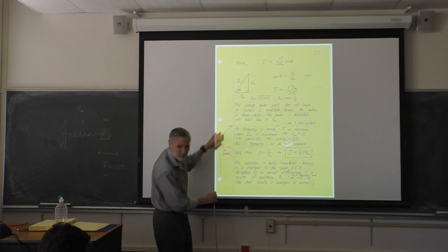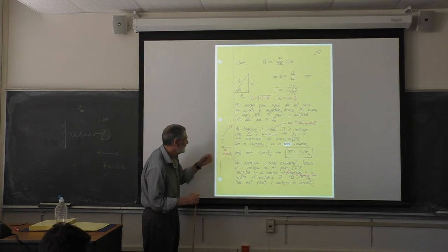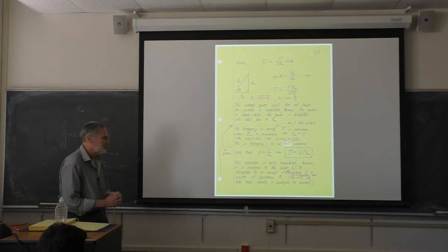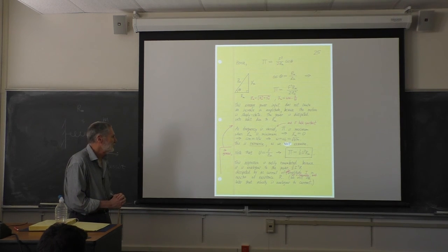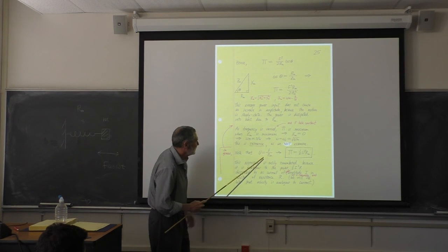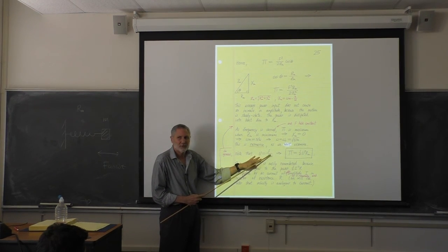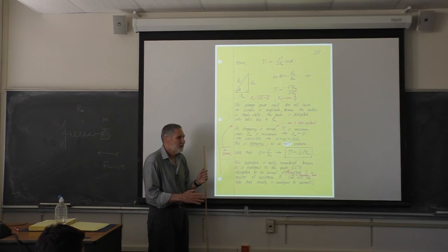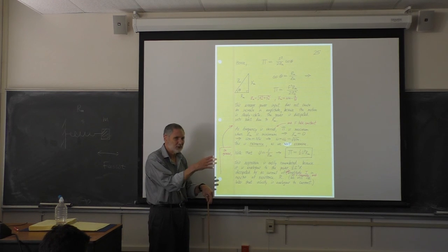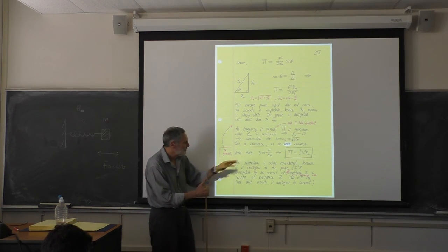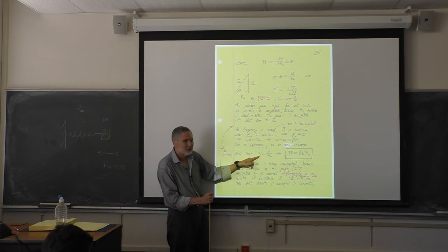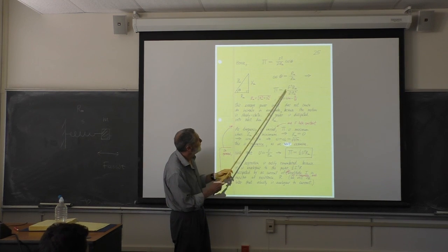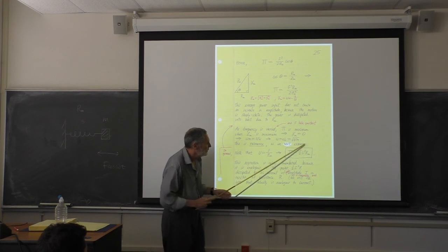Okay, now we're supposed to go here. So here's the boxed expression that you've been anxiously waiting for. And I can tell you, you forgot, but that's okay. We can make an interesting step here. Remember this? This is really the usefulness of the impedance. We take the complex impedance, being the ratio of the complex drive divided by the complex response, take the magnitude, and this tells us what the velocity amplitude is. We've seen it before, it's simple. I can use this and substitute it into here. And you'll notice this is squared and this is squared, and we get this.